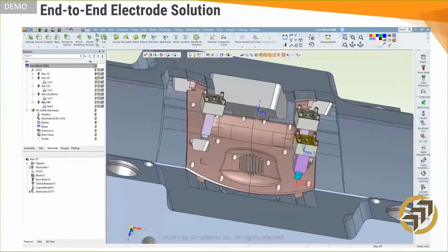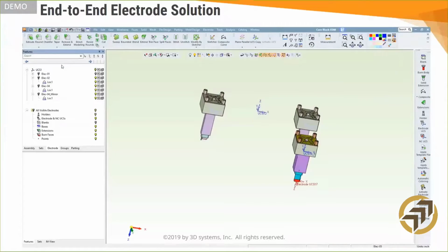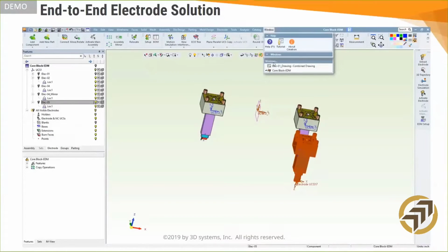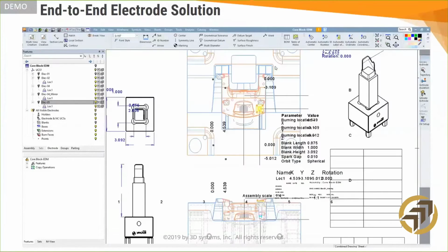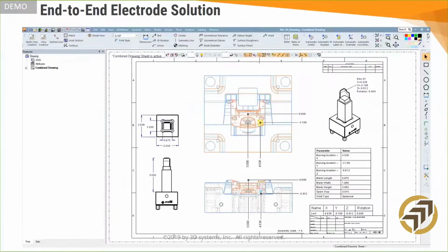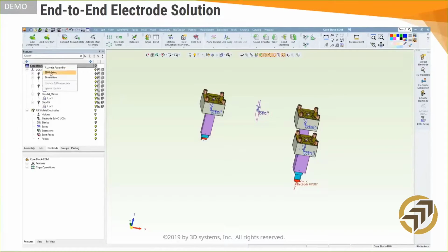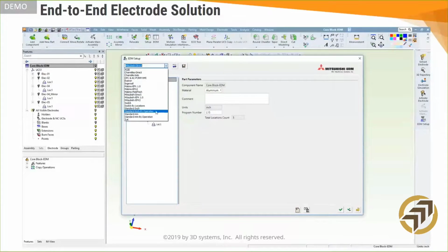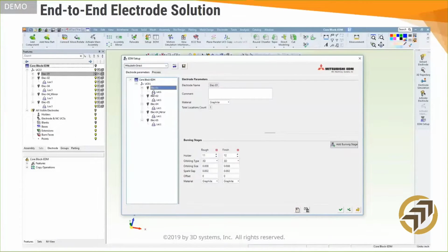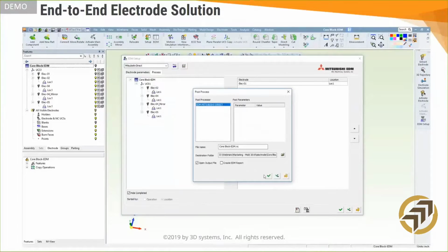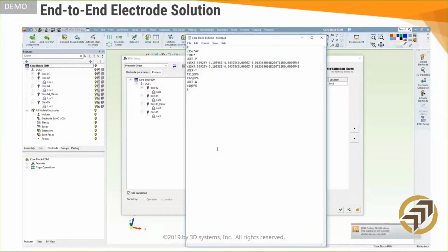As electrode design progresses, you want to get that information out to the shop floor. For some, that means creating electrode inspection and location drawings. This too is an automated process, using a set of options that understand electrode shape and a drawing template that you can easily modify for your needs. Other tool shops are now posting electrode data directly to the EDM machine. The options in the post interface will vary depending on the machine manufacturer, but usually include the type of orbit, size of overburn, and number of tools. Posting directly to the EDM machine assures an error-free transfer of the burn location dimensions and trajectories.